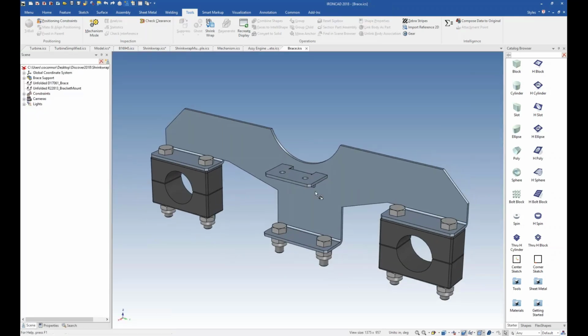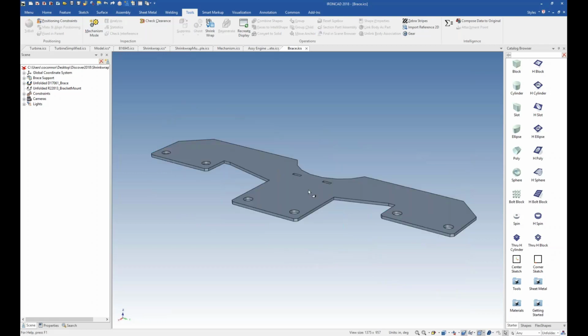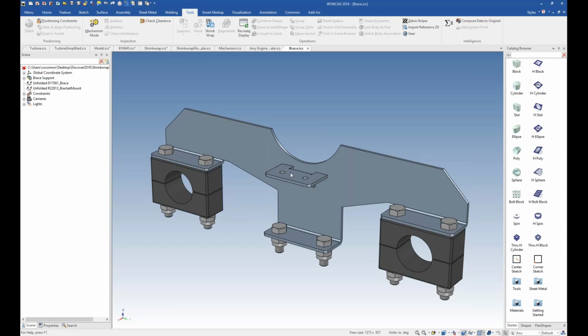And basically we have a couple sheet metal parts and some other objects inside of here that if we click down to these parts, you can see that we can actually unfold this and see the unfolded flat pattern for this object, and we can get back to the folded pattern as well. And this is a sheet metal part as well. And what we want to do is actually take this into the drawing. So we want to have a single drawing basically, and a couple sheets to put these on, and a bill of material on these.